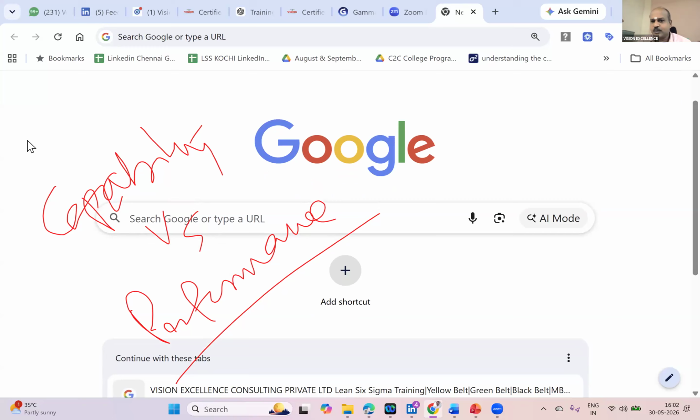your PPK and CPK should be more than how much? 1.67. So I assume you achieved 1.67 for CPK. You achieved 1.67 for PPK also. You have achieved the maximum potential. You understand, all of you? See, further, if CPK is 1.67, then your PPK can maximum become 1.67 only. If your CPK is 2, then your PPK can also maximum become 2.